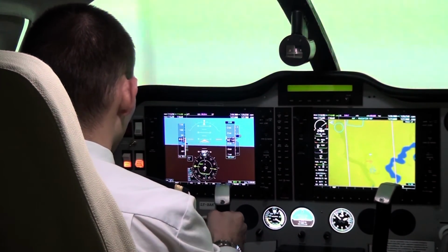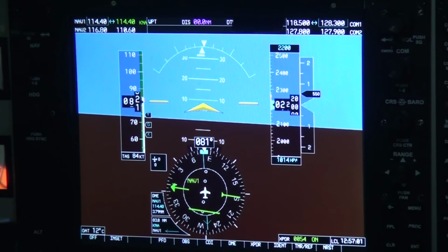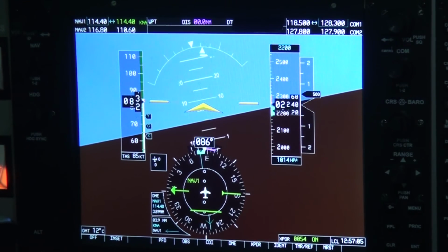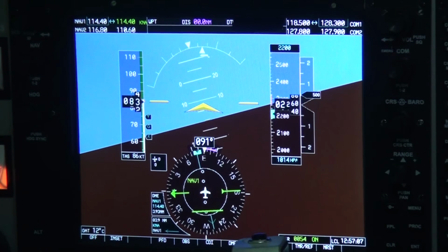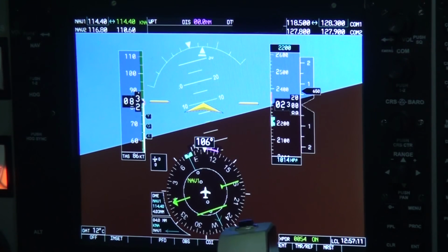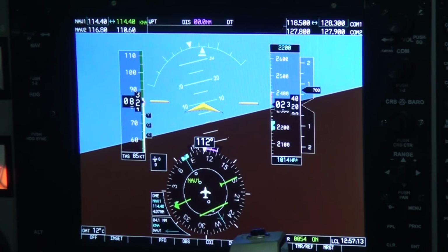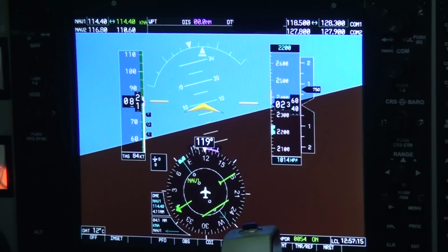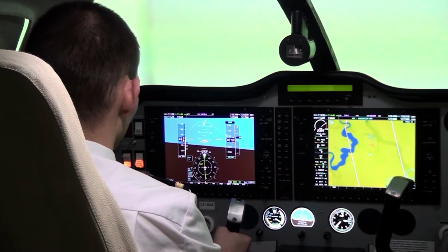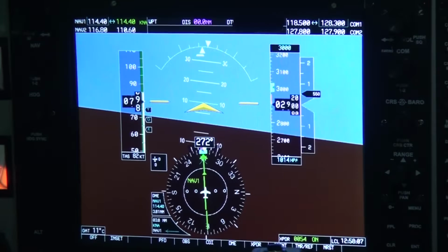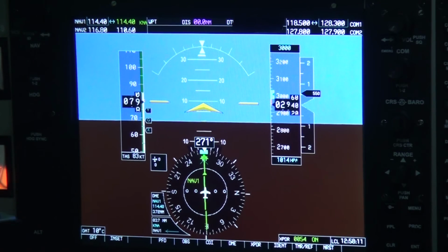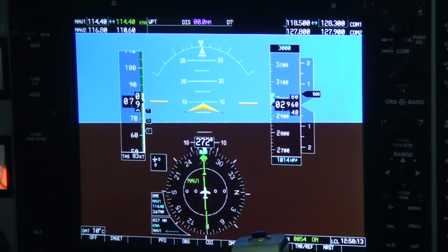We are almost on 2200 feet. Let's turn right. Continue climbing 3000 feet toward Kilo November Alpha. Select your altitude and continue climbing. 3000 feet, level off. Reduce RPM.